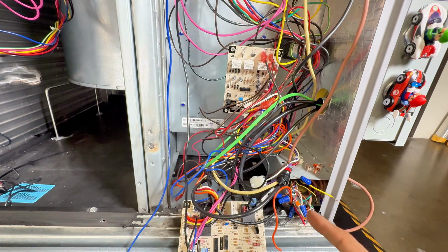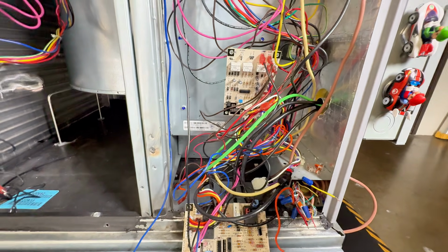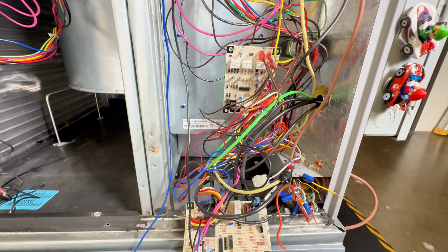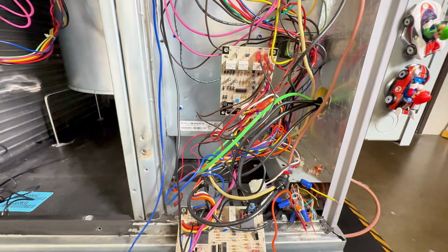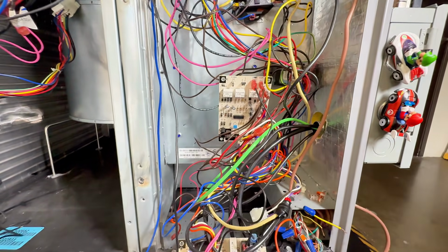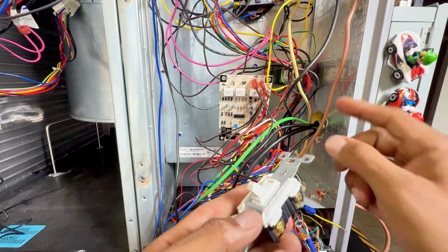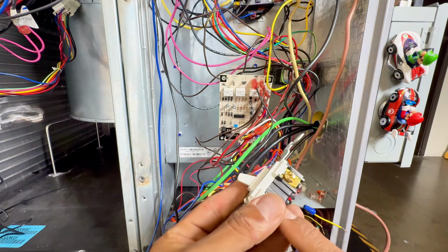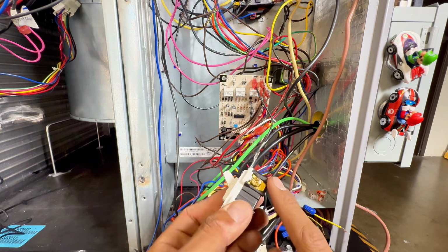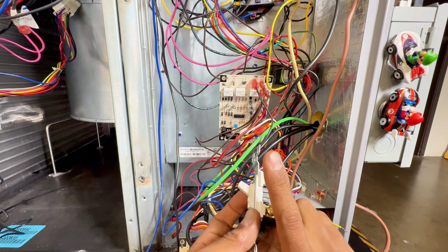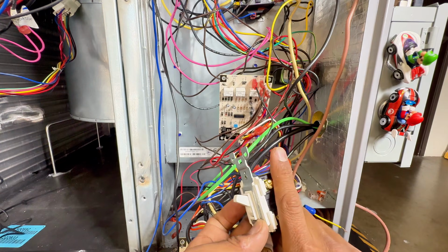So in this case, okay, let's take the path. Let's do the easy one first, Luigi, okay? So Luigi, when we have a call for cooling, right? On your thermostat, internally, you got 24 volts here, and then it does this, boom. And then that 24 volts is supplied to my yellow and my orange at the same time.